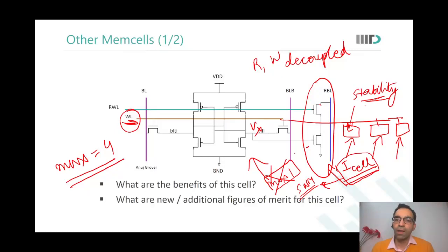Yes. Over here, I can have both the pass gate and the pull down large enough. So in the same area, I don't need to have any constraint sizing on the pass gate, and therefore I can have more read current. Yes, sir. Are you able to see this?